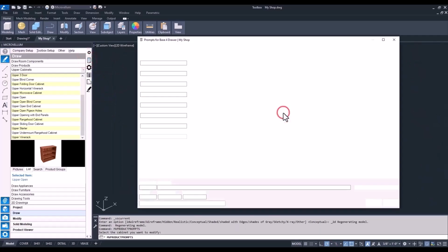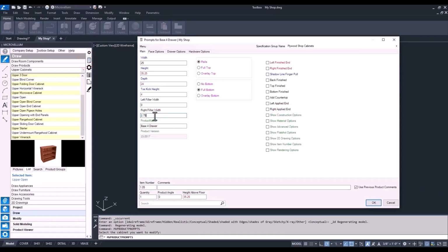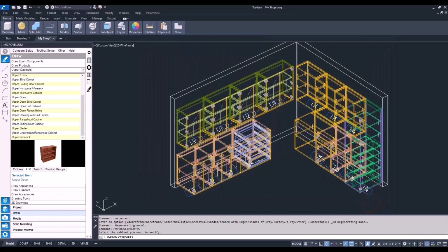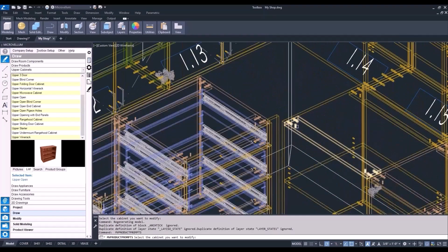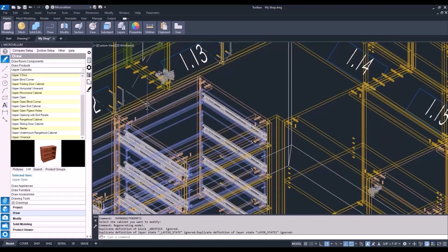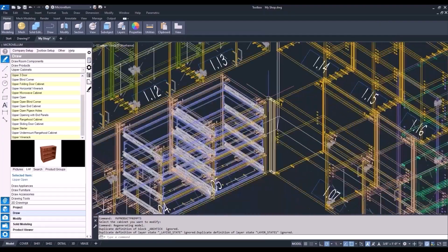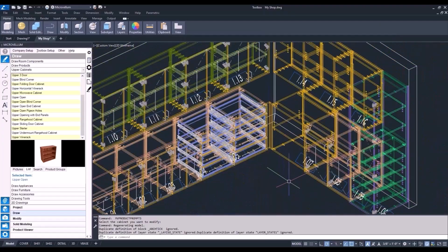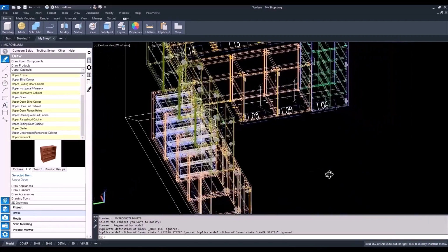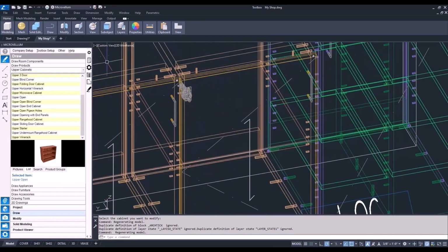So we're going to stay here with the base cabinets, go over to our drawer stack and set a filler width. Instead of using our corner filler product, we can just set a right filler width on that cabinet and then the left filler width on the other one, and just plan on screwing that together on the job site. So it's not a separate product that we would need to send out to the shop for production. Now changing this cabinet to a right swing.